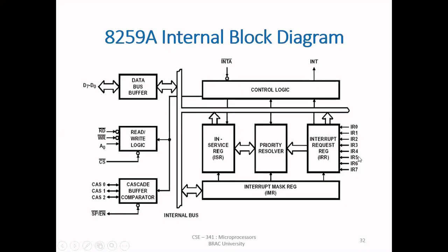It depends on my desire. Again, if I connected a monitor and it wants to send any kind of interrupt, then it will send it by IR3, etc. So whenever any of the interrupts come through these 8 pins, then the INT output pin will be high.